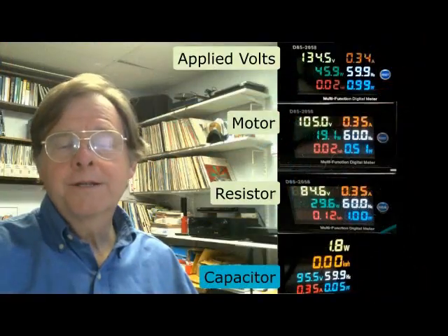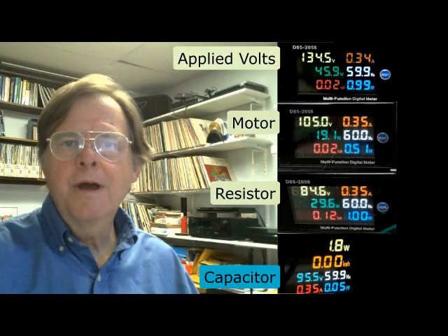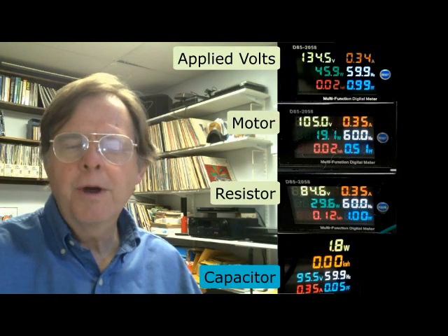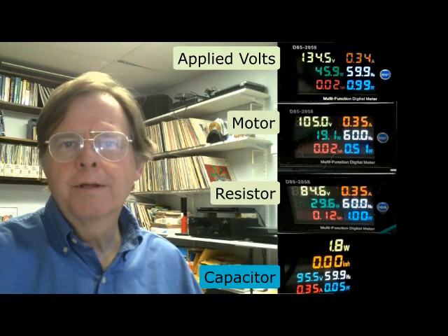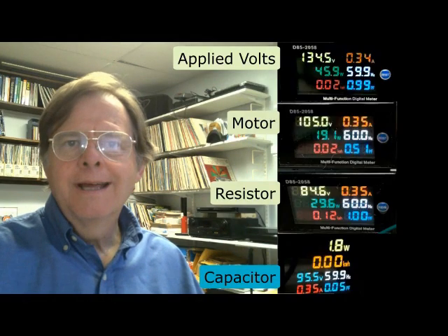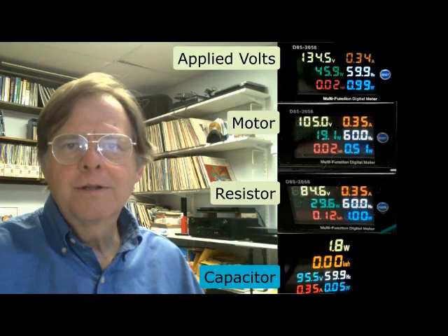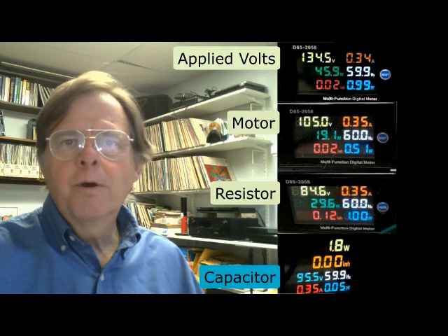If you have paid attention, you've probably noticed that the sum of the voltages of the individual components add up to more than the original applied voltage. This does not mean that magically the circuit is creating voltage, but where does the extra voltage come from? The AC current flowing through the motor is constantly changing because it is an AC current. This creates a constantly changing magnetic field, which generates a new voltage, and this voltage is called a reactive voltage. It is, in fact, inductive reactance.